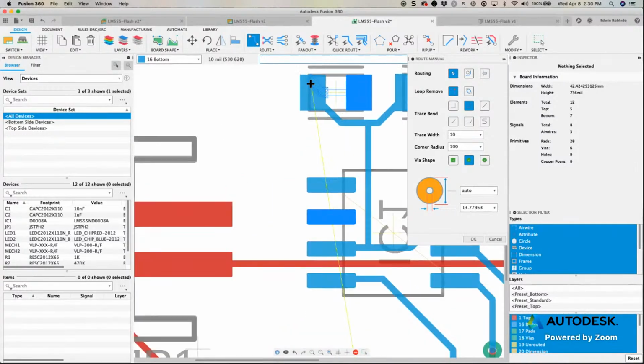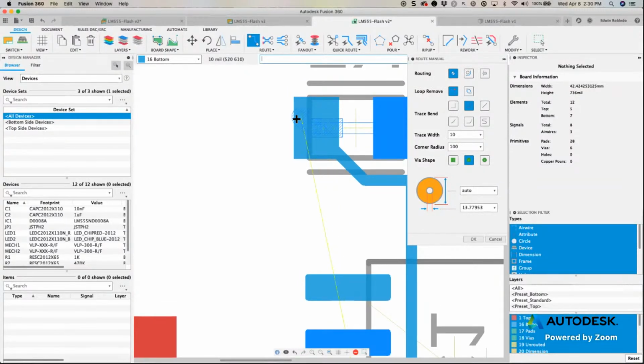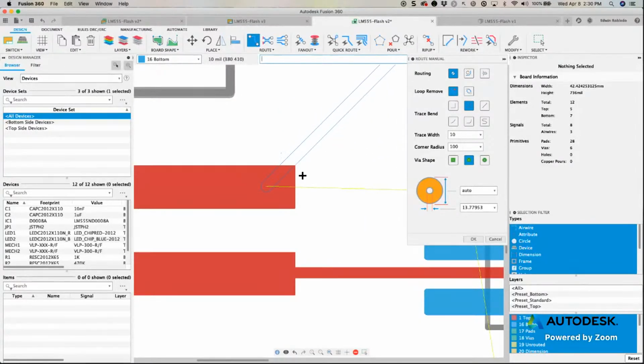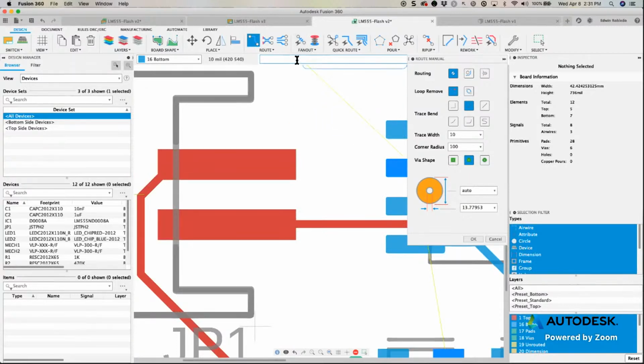And as you can see, as soon as I start moving into an area which is a violation, we get those hatch marks. Let me go above a red because that way you can see it. Let me switch layers. And as you can see, I get the violations immediately. This is a parameter that you could actually turn off, but we strongly recommend that you do not turn this off. It's really a good idea to always keep this on because in real time, you will be able to see what your DRC errors are immediately, okay? I just wanted to bring this up as well. Let's go back to DRC.